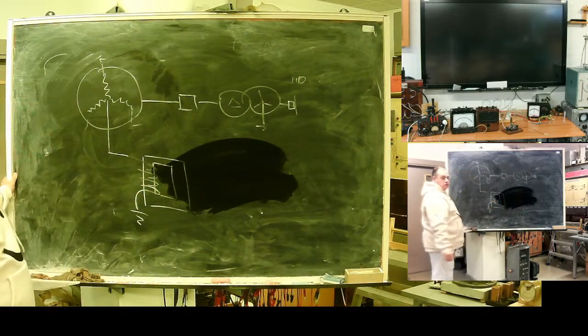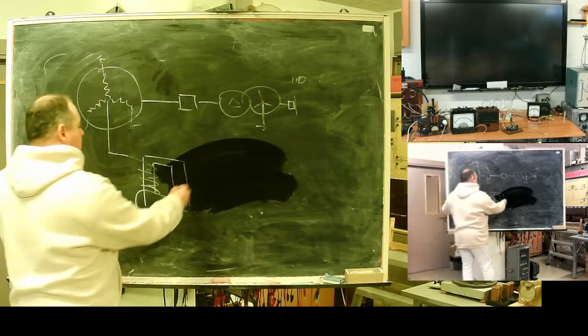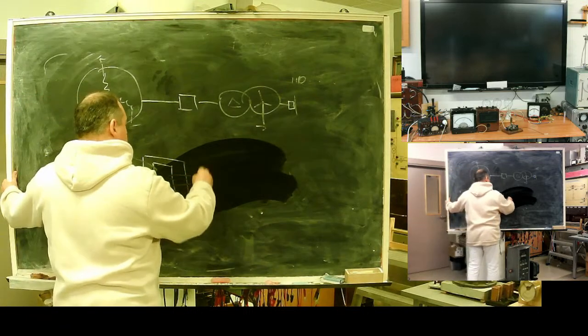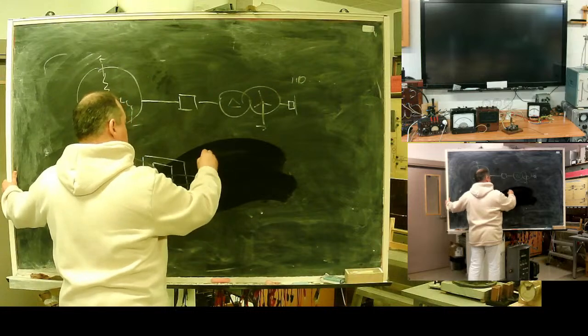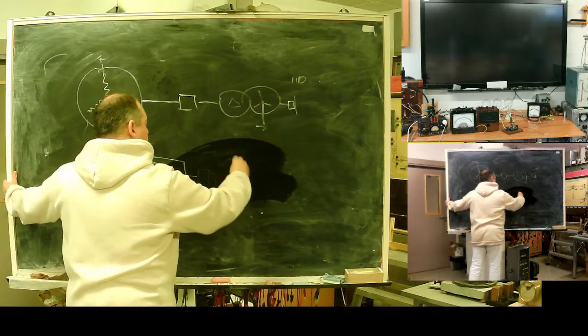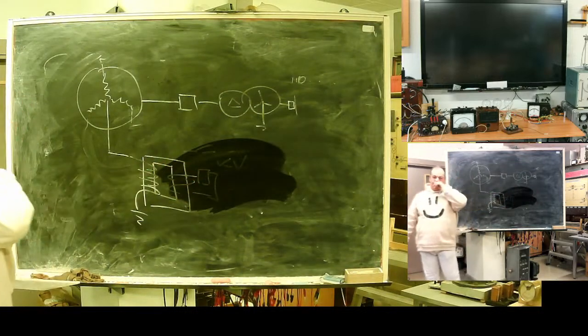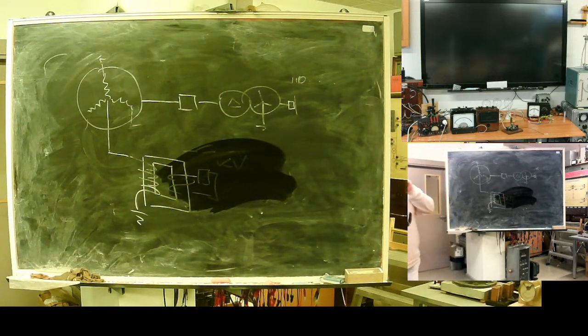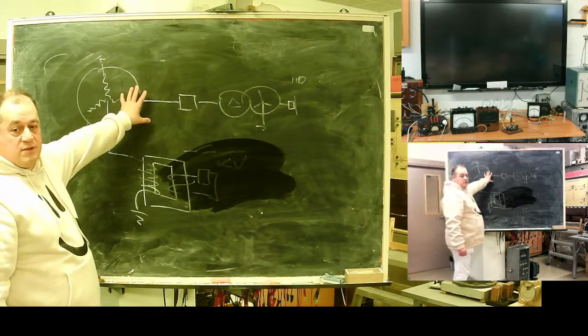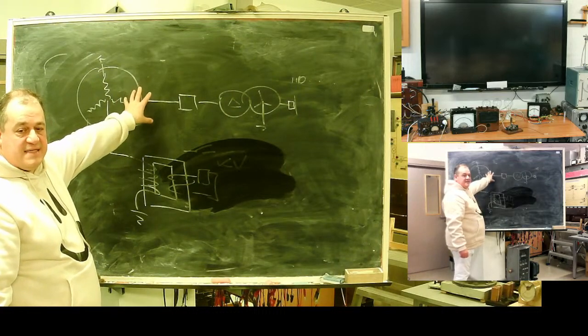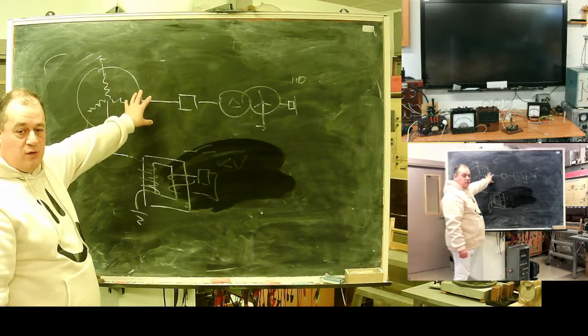Neutral is connected to the ground via voltage transformer. Schematically, this is a voltage relay, a neutral displacement relay. It signals isolation fault of the stator. So the generator operates in the isolated neutral network.